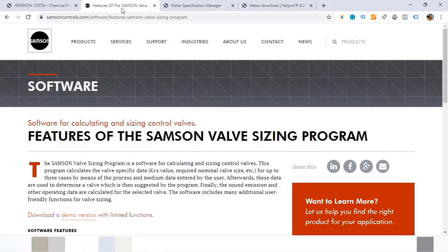You don't choose a pipe with 5.35 inches inside diameter, even if it is the best inside diameter that you need to have the right velocity of flow and the better pressure drop, because suppliers do not fabricate that kind of pipe. You need to choose a standardized pipe, and it is very similar not only for control valves but also for PSVs.